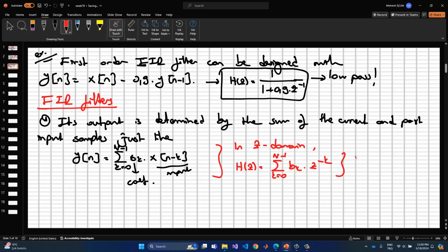In this case we don't need to check the poles, because if the input is bounded, this yields a bounded signal, since it is the open loop response. But in the previous case we had the closed loop response, or feedback, and this feedback may continue to grow or decrease in value with respect to the input signals. In the FIR filter we don't have any stability issues.